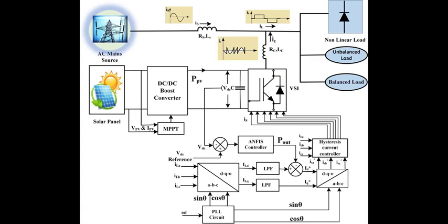Notch filters. Notch filters are used to attenuate specific frequencies or frequency ranges. They are employed when there are known frequency components or interference that need to be eliminated from the system's output. Anti-islanding filters. These filters are a critical safety feature for grid-connected systems. They detect islanding situations when the grid goes down, but the renewable system continues to generate power, and they disconnect the system from the grid to prevent feeding power into a potentially damaged grid.